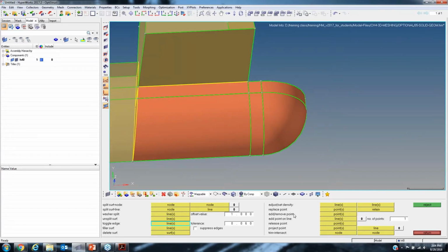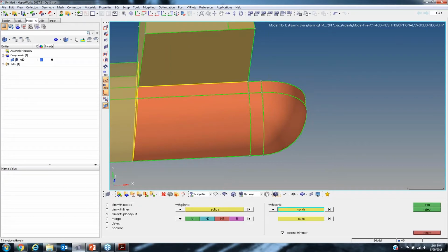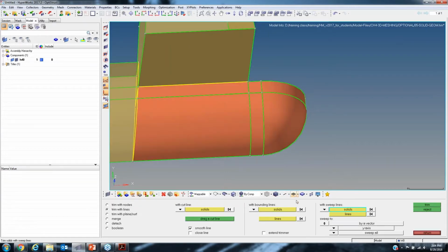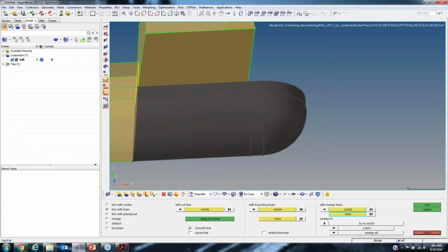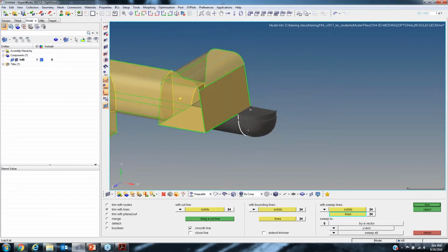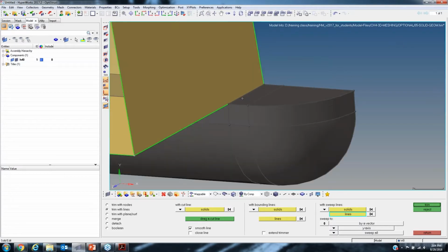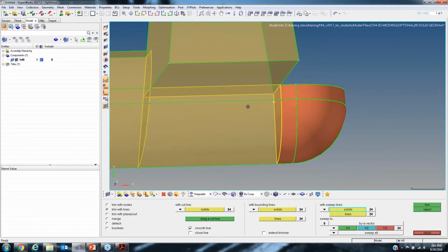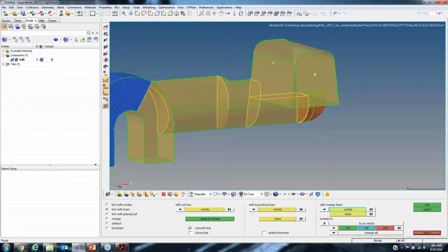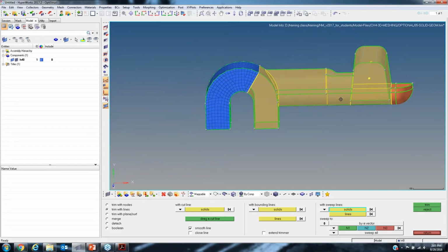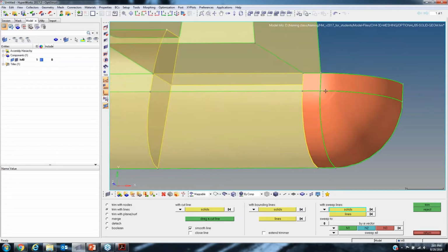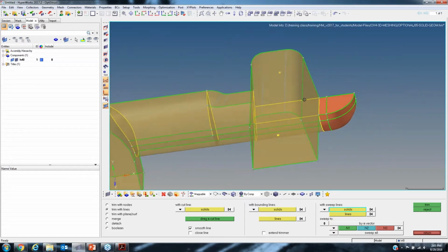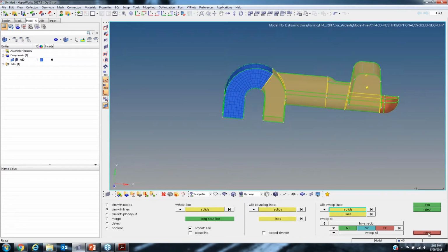So just go ahead and use solid edit again. Select the solid. Actually, we're going to do lines. So select with lines. Actually, we'll select this line on top. And I will select direction using N1 and N2. And that trims it. And now you can see that we have most of it mappable now. So now that you've separated most of the solid, I can go as far as separating this as well. This takes a little more time, but that gives you a fairly good idea.